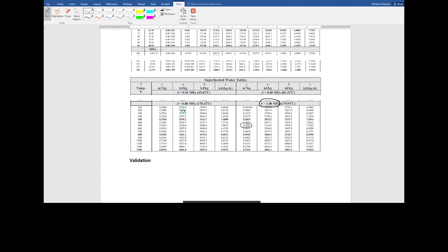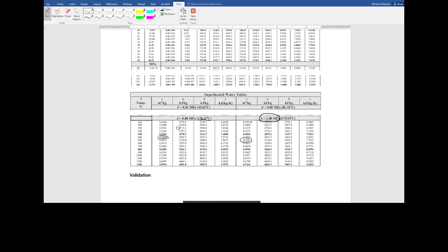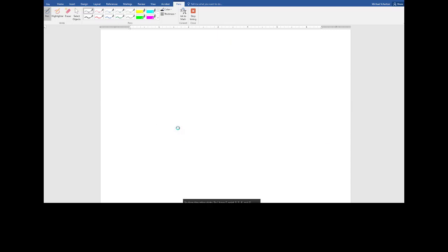If we're talking about state 2, it was at 8 bar or 0.8 megapascals, and it was at 400 degrees. Here it tells me that water boils at 8 bar at 170 degrees, or a little bit more than that, but 400 is much bigger than that still. So here, this is 0.384. So I have 0.354 and 0.384.